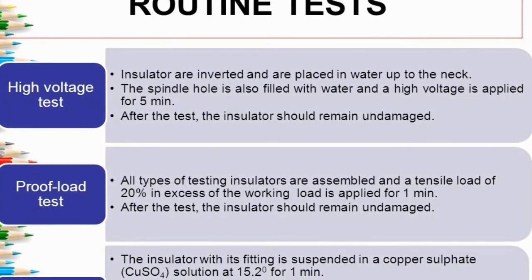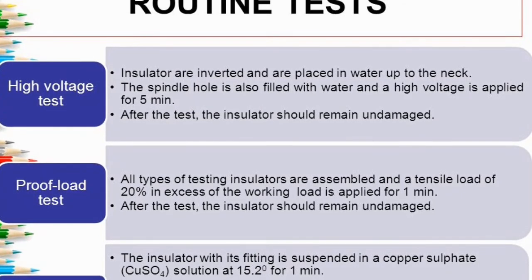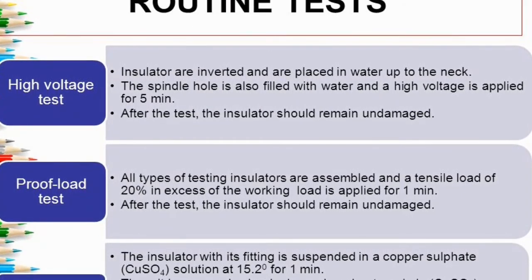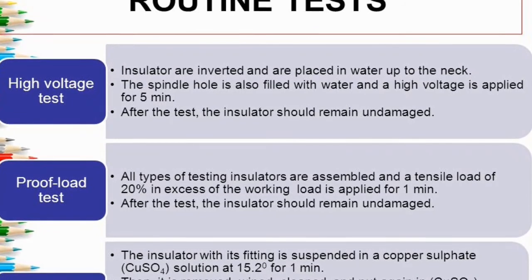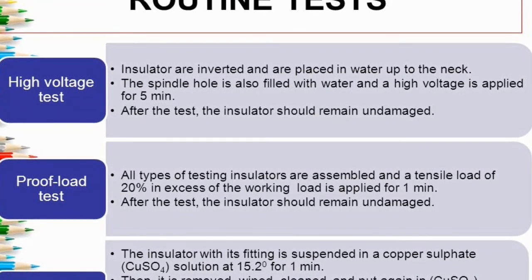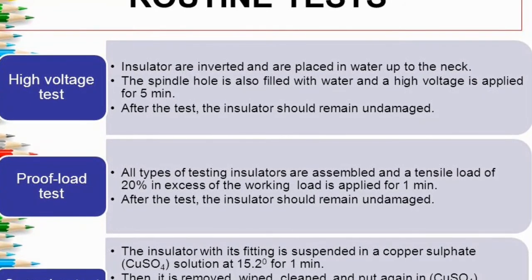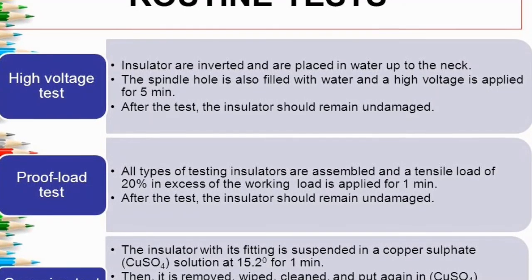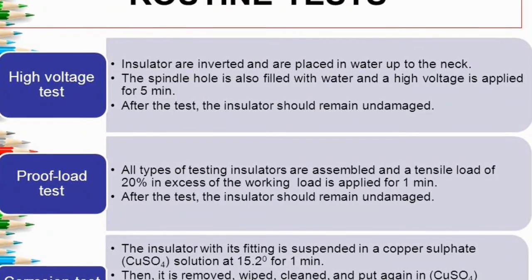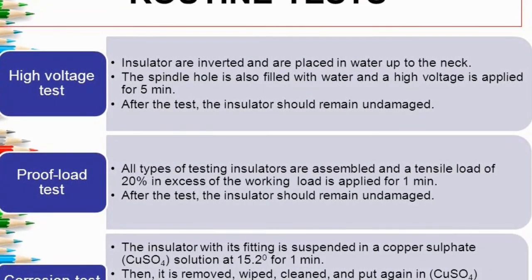So in the proof load test, after gathering all the insulators, 120% of the working load is applied to them for 1 minute, and after that the insulator should be undamaged, otherwise it won't be suitable for working conditions.